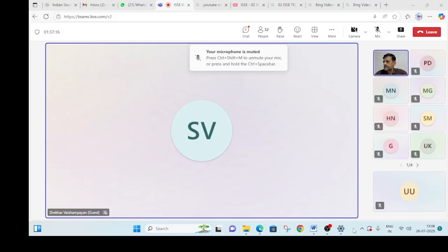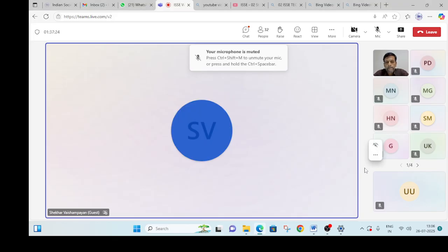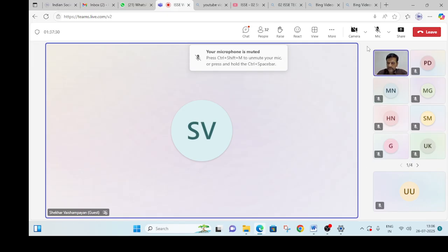So the role of the geotechnical engineer is to provide you the geotechnical design. It should give you the length. It may not define the reinforcement in the pile. It can, though. The geotechnical engineer can help the structural consultant or engineer by offering a choice of using different combinations of structural reinforcement steel. But the final decision about placing the reinforcement will be taken by the structural engineer.